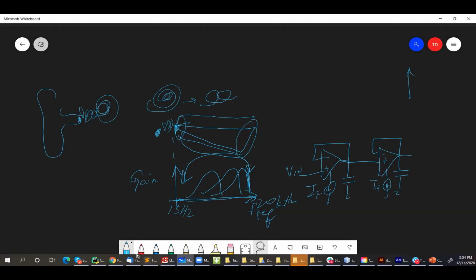And so if I now plot the frequency response of this, so you can do omega this time, right? Then what you get will be something that looks like this. It's a low pass, no ringing. And this would be 40 dB per decade because it's a second order filter. But you'd like to be preferential for some smaller set of frequencies, right? So which means that now you have to make the filter a little bit peaky. And so you'd like something that looks more like this, right? With a little bit of Q.